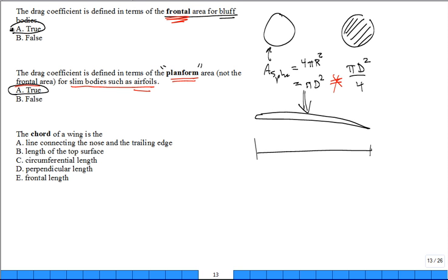So be careful when you have drag coefficients, because the area for a blunt body or a bluff body is different than the typical area for a streamlined airfoil body. Okay? And why did they do that? Because in this body, what dominates the drag force? The two competing things, what dominates? The viscous, the viscous. And then for this object right here, the bluff body, the blunt body, it's not viscous drag that dominates, it's the pressure drag. Some of them call it form drag, but form is not very formative. Form meaning it's due to the area because of a pressure difference on the side.